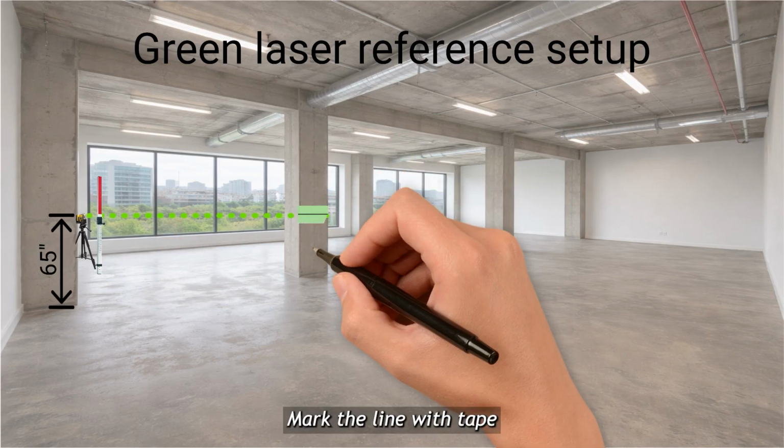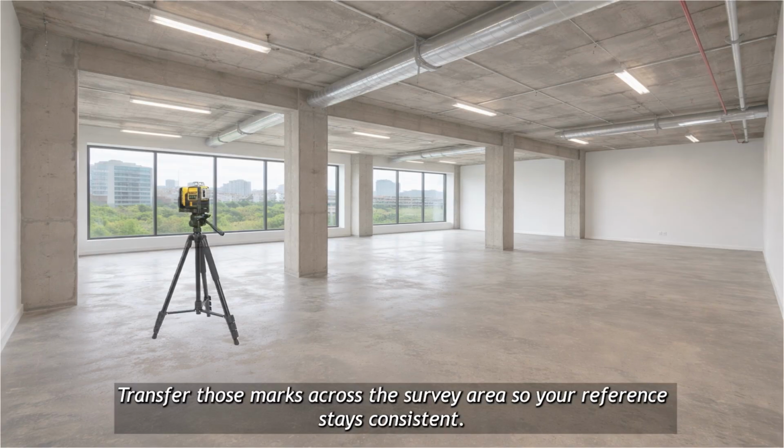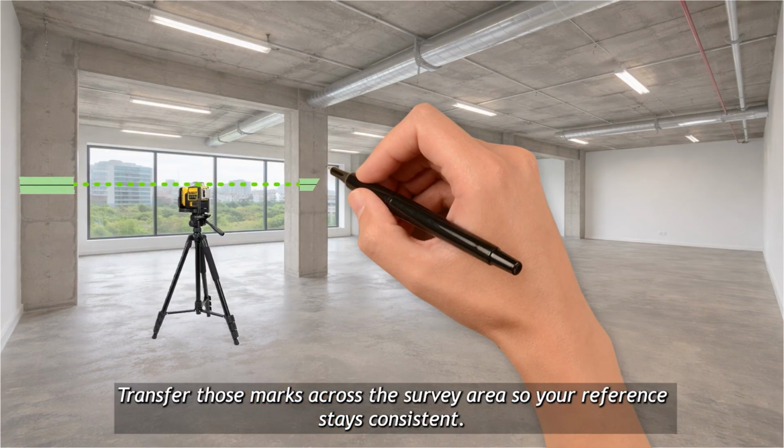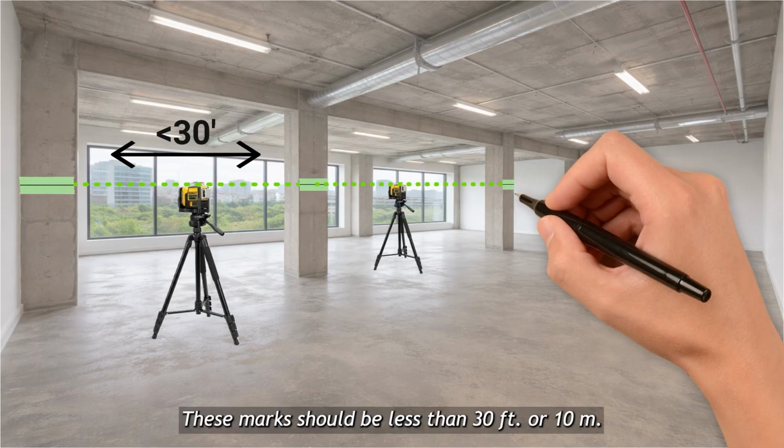Mark the line with tape, and keep your marks close enough to stay visible across the space. Transfer those marks across the survey area so your reference stays consistent. These marks should be less than 30 feet or 10 meters apart.